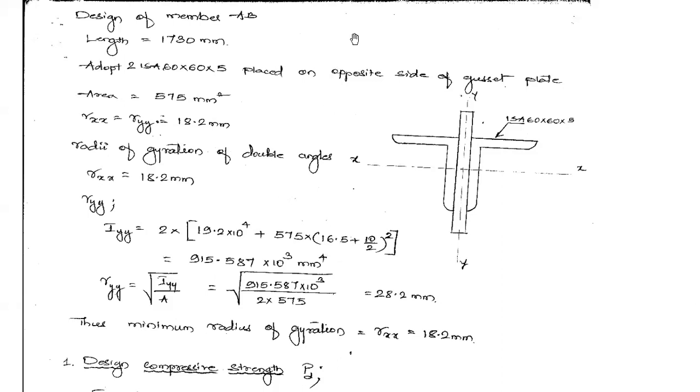That is what the parallel axis theorem states. So this is the centroidal axis of the single angle section somewhere over here. I can get this distance CYY. In the steel table, you will find CYY mentioned over there, so that can be obtained from the table.